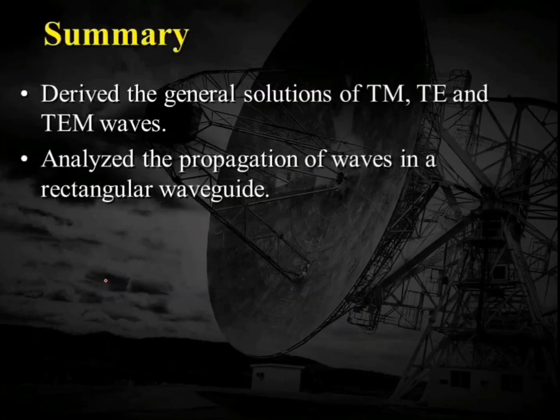So at the end of this lecture, we can conclude that we have derived the general solution of TM, TE and TEM waves, and we have analyzed the propagation of waves in a rectangular waveguide, where we have concluded that TEM wave does not exist inside a rectangular waveguide.